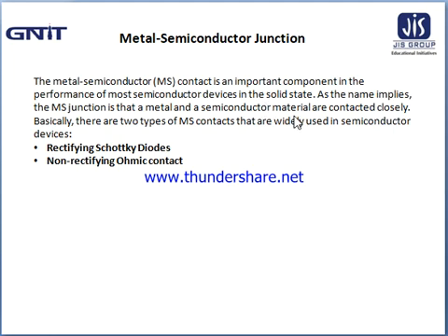If a metal and a semiconductor material are contacted closely, basically there are two types of metal semiconductor contacts that are widely used in semiconductor devices. The first one is the rectifying Schottky diode, and the other one is the non-rectifying ohmic contact.